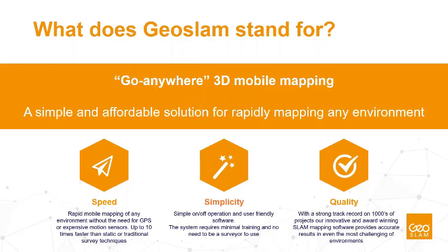Second, simplicity. We also put a big value on ease of use, so that any operator, not necessarily an expert or any surveyor at all, can use that technology. He just needs to switch it on, set a fixed position, initialize, and then go on in whatever environment he needs to survey, in the range of 30 up to 100 meters, and then close the loop at the same point where we started.